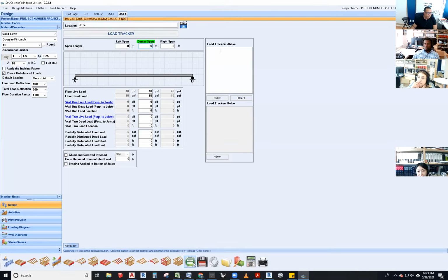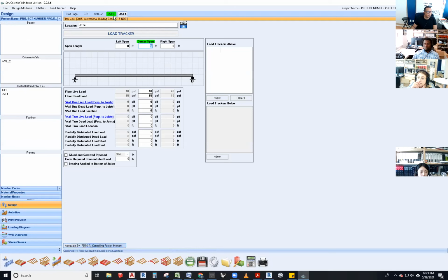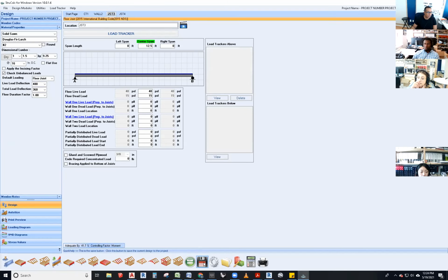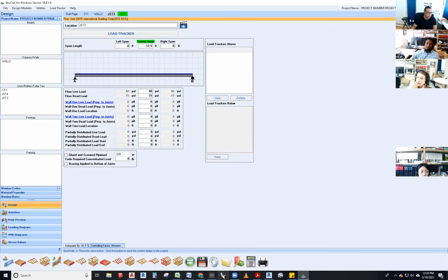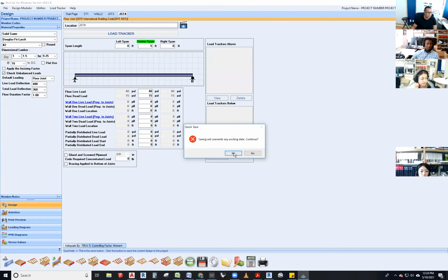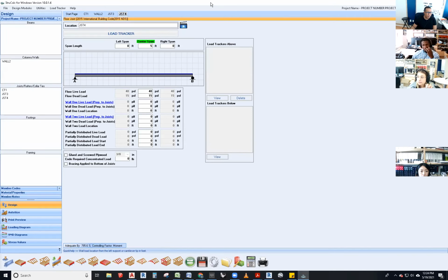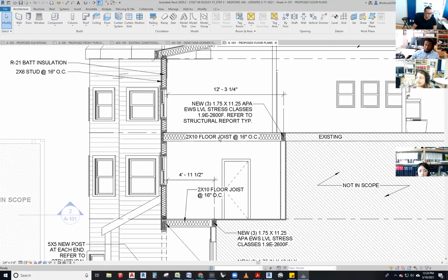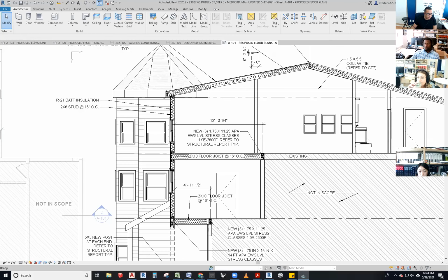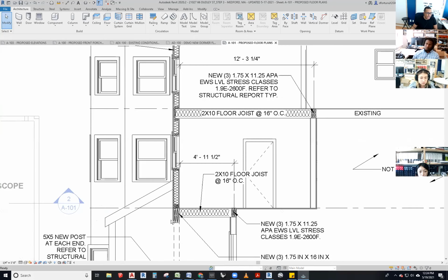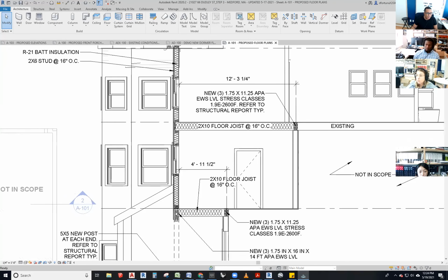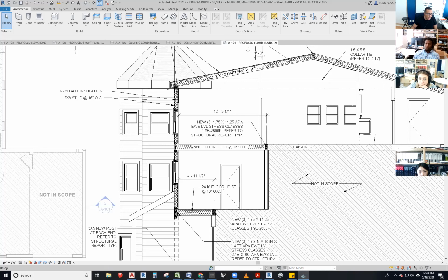And we're gonna save it. So we already have joist 3. We already have joist 4. Right? So we already have sized this joist and this joist, and we've already sized that wall. So now we can potentially size this baby right here. Why? Because we already have loaded that guy with this guy.